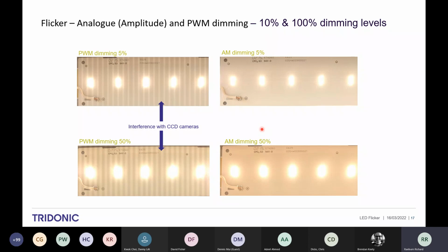If you're using 25 frames a second, PAL, you don't see it. If you use that same mobile phone in the United States, where they have 120 hertz flicker, again, you won't see it. But here you will. It's 30, 60, it's not a divisor of the flicker frequency.